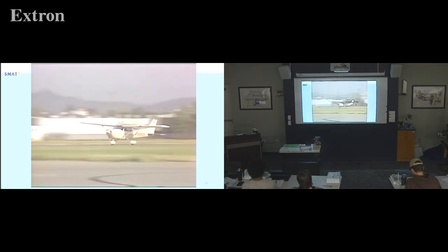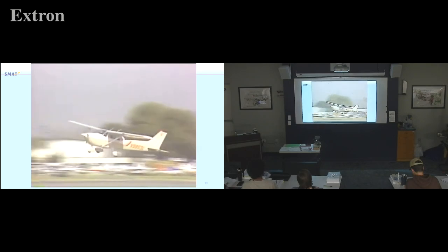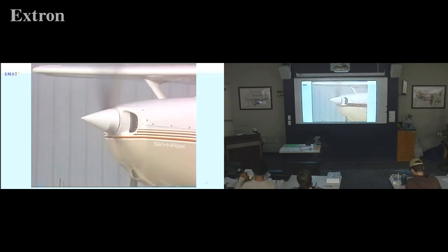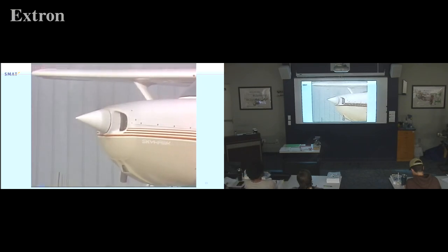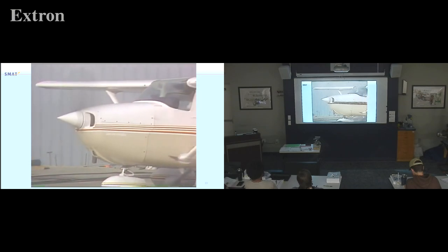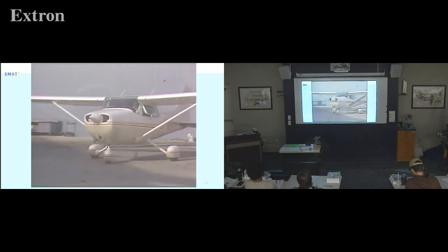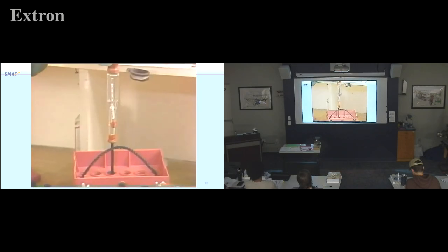If aircraft service consists largely of short flights and frequent engine starts, check the battery more often. Slower spooling speed and higher starting temperatures may be an indication that the battery could require recharging or replacement. It may also be the result of poor battery connections or other aircraft component problems.